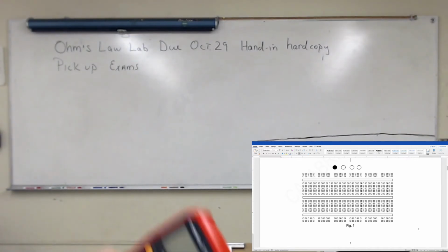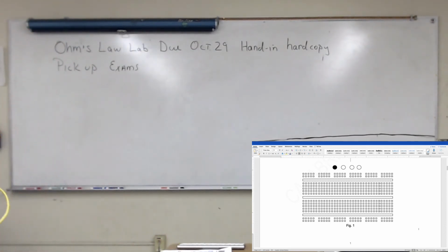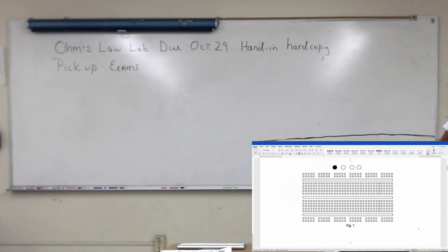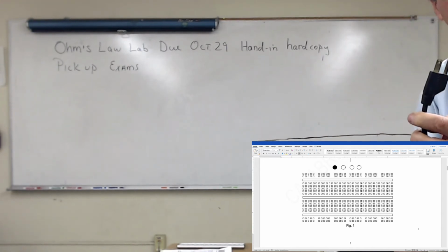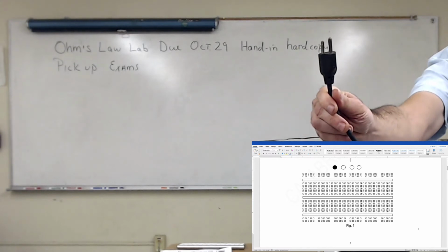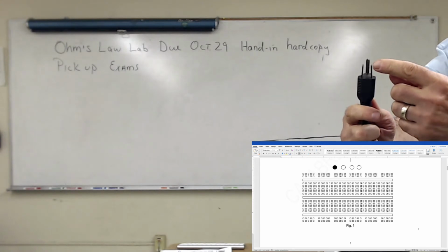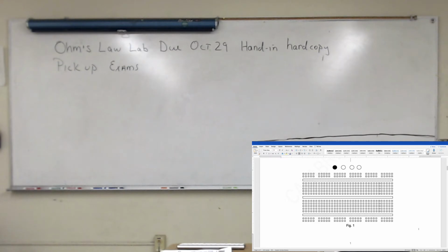And one of the things about the multimeter is it gives you an idea that you can use this as a diagnostic tool. So for example, let's say you plug something in and all of a sudden it stops working and you suspect the plug, or your wire, your cable that goes to your electronic device. Okay. One of the things you can do to test is to measure the resistance between the two prongs. If the resistance is 0, something is shorted. Something is wrong with your plug.